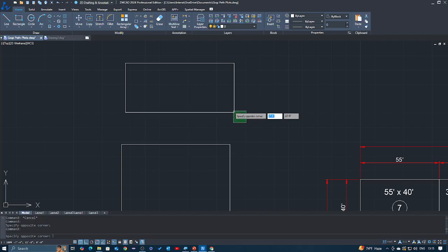So whichever objects are touching that area, only touching, it's not including. So in the blue selection area, you have to cover the complete object inside the blue selection. But in the green selection area, you just have to touch that object or segments, then click the next point, and the two elements or two lines are selected. Just click and click. This is the difference, guys.